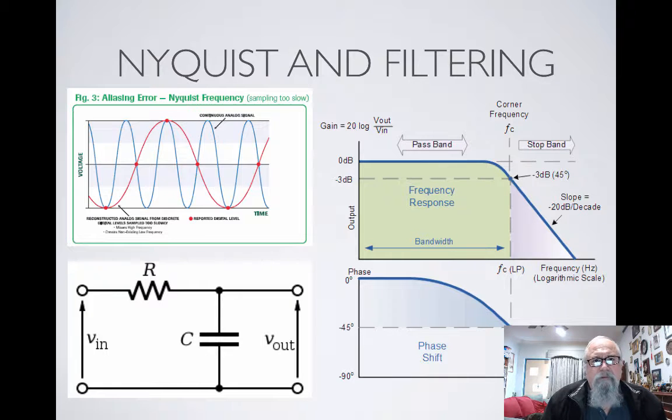The way we achieve this in its most simplest form is a simple resistive capacitive network. A resistor is a linear device. It is not susceptible to anything in the frequency spectrum. So whatever frequency we put in, it will attenuate or limit the current flow across the spectrum equally. A capacitor, however, has a high impedance at low frequency and a low impedance at high frequency.